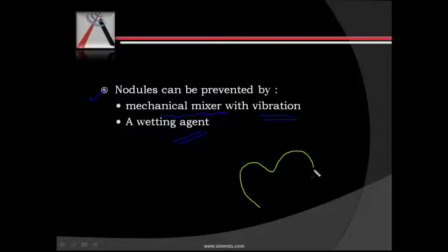If we put the wetting agent on the wax pattern, this wetting agent will help the investment that we pour on top contact the wax pattern thoroughly, so it will not leave room for the air in there. But we have to be careful that the thickness of the wetting agent doesn't cause defective surfacing itself. So this wetting agent has to be applied in a very thin layer.